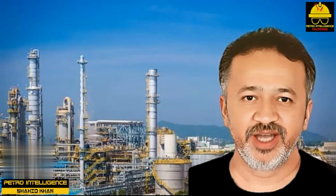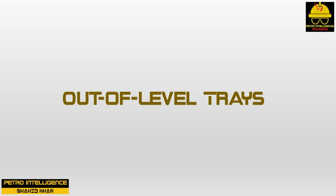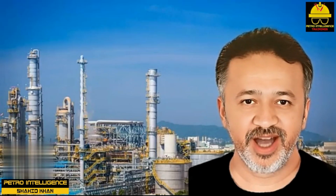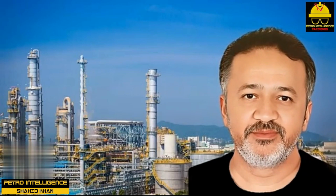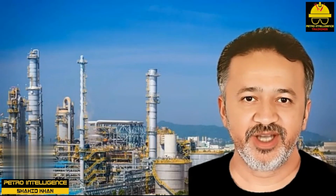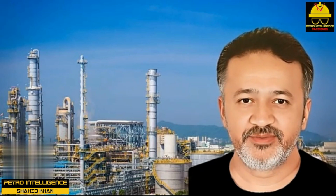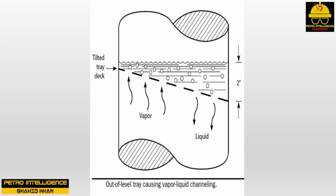Other causes of tray inefficiency. Out of level trays. When trays weep, efficiency may not be significantly reduced. After all, the dripping liquid will still come into good contact with the upflowing vapor. But this statement would be valid only if the tray decks were absolutely level.